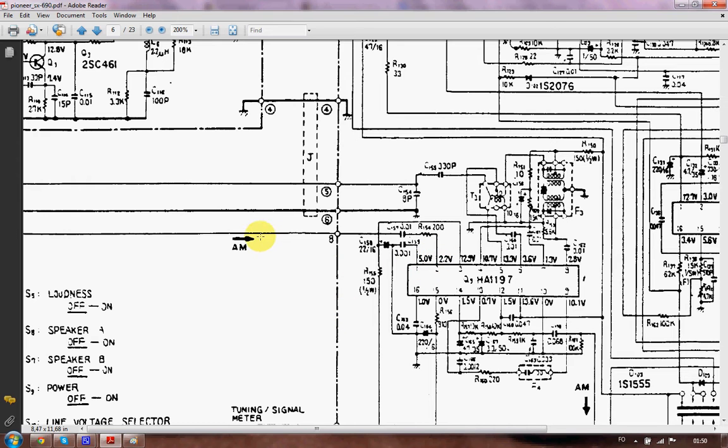Since it's not amplified, you would not expect a large curve at all, but you would probably set your oscilloscope to your lowest setting and see if you could see anything like a wave, because if you didn't, it would tell you that you have no AM input.